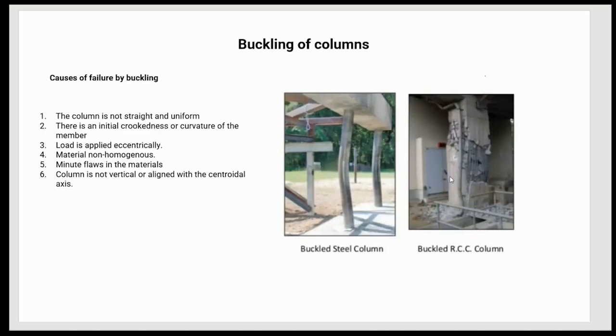So we know, for example, that concrete is very good to be used when compressive stresses are present, because the compressive strength of concrete is wonderful. The tension resistance of concrete is lousy. So this might be that the buckling produced in this column was such, that's my assumption, that the tension strength was overcome by the forces applied here.